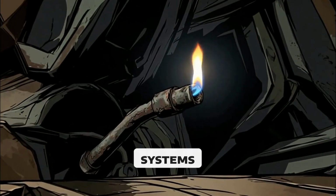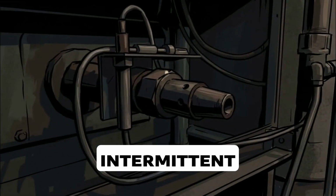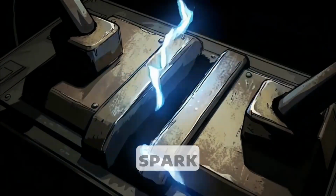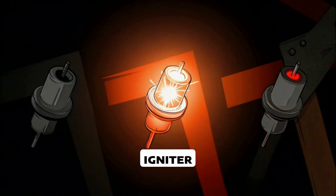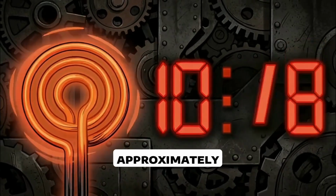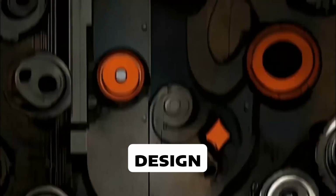Now, ignition systems. A standing pilot burns continuously. An intermittent pilot lights only when there is a call for heat. Direct spark ignition uses an electrical spark and no standing pilot. Hot surface ignition uses an electrically heated igniter. Many hot surface igniters warm up for approximately 10 to 30 seconds before gas is released, depending on design.